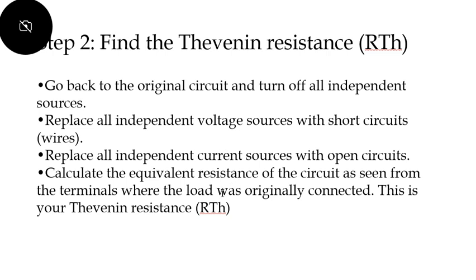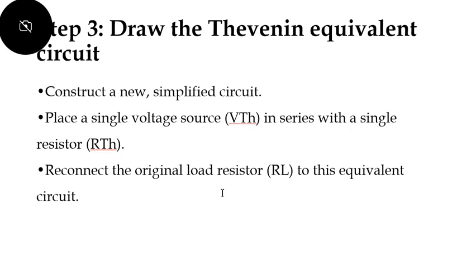Then calculate the equivalent resistance of the circuit as seen from the terminals where the load was originally removed. You have to look at the terminals where the load resistance has been removed. This is your Thevenin's resistance.